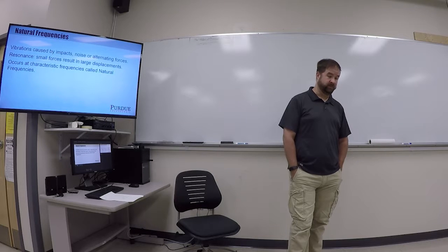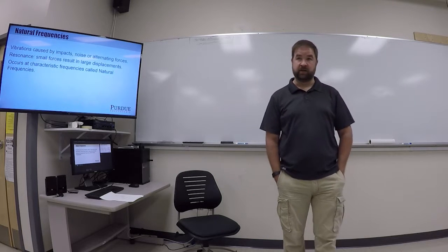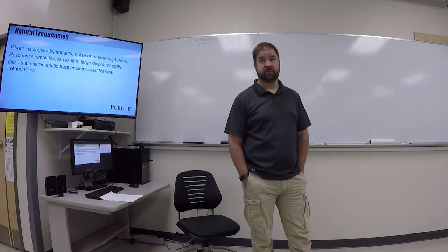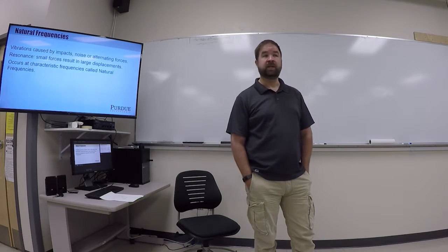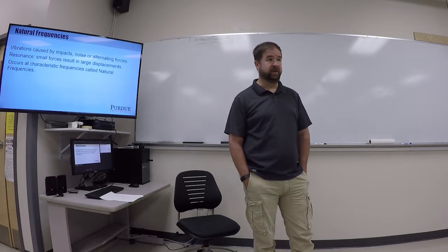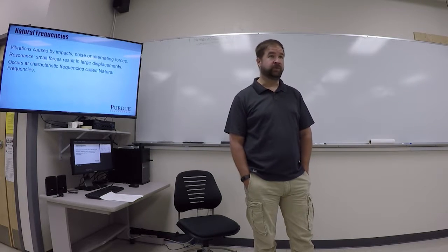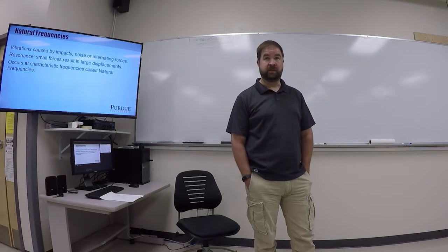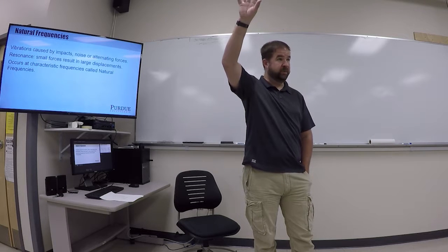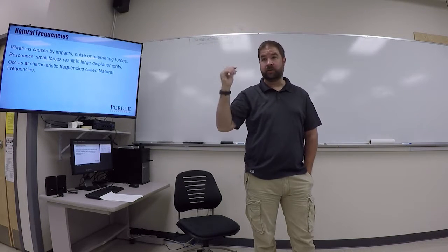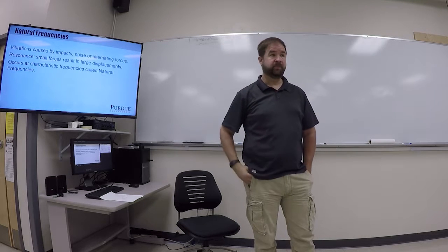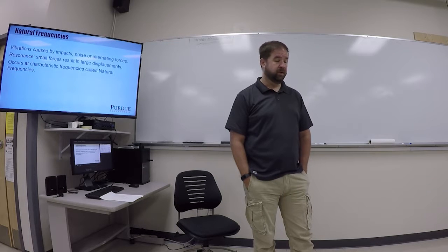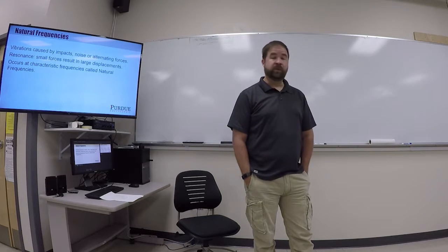So with a conventional elevator with steel cabling lifting the elevator, our current limits are about 1,600 feet, which means that we've got buildings that are taller than that. And thus, you can't ride the same elevator from the ground floor to the very top. And so what that means is they have to have some lobby halfway up that people get off the elevator, switch elevators, and then continue on going up, which obviously is inefficient and annoying and so forth. So people are trying to get around that.